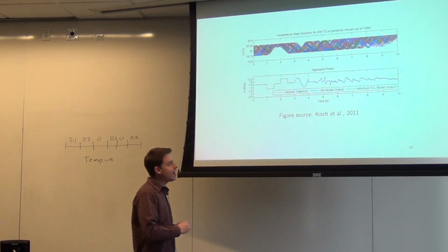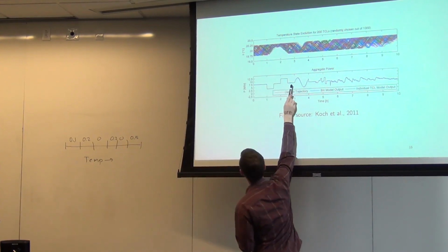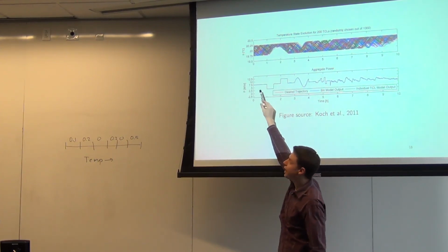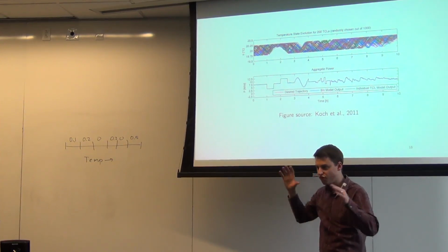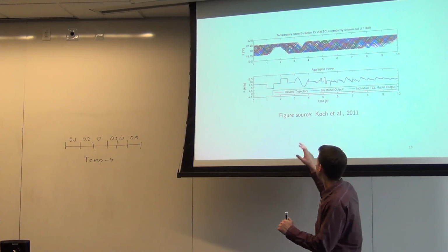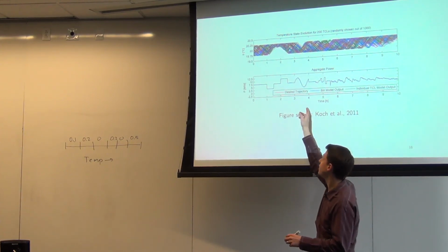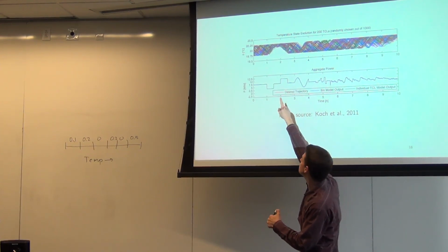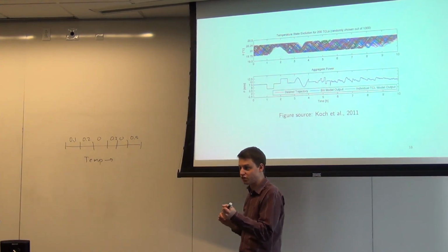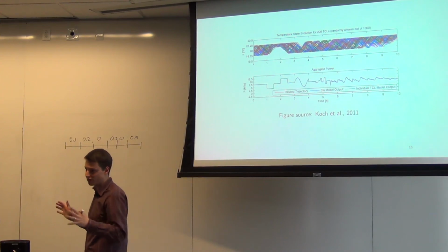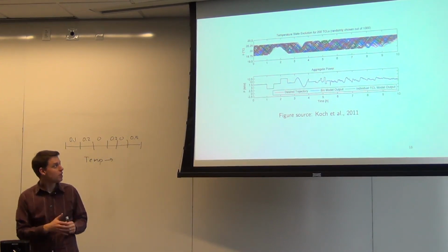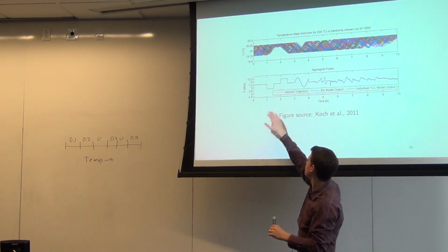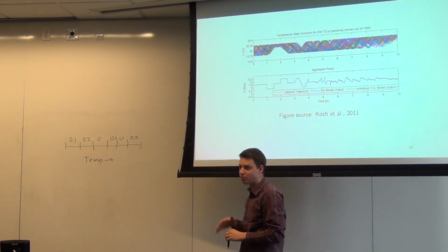What they show is that if they have desired trajectories to follow, so this is the red here, which you can't even really see because the result follows it so well, is some desired trajectory that they want to follow for the sum of all the refrigerators. And what they show is that using this simple kind of control law, they can track this very accurately, even though what everyone is actually doing up there is very different. So that graph on top shows you where each of those air conditioners are. And that varies a lot because they're all doing crazy stuff. One may not be able to turn off at any given time. But in aggregate, they're able to track these either steady or oscillating or random patterns of desired power output from all of them.